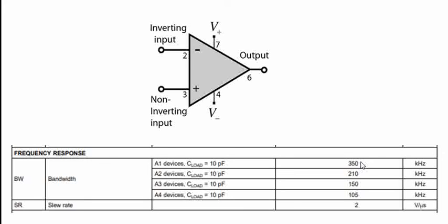While not all applications require it, definitely for inputs having a varying signal, where the variation is faster, you need to consider the bandwidth scenarios and then use the op-amp.